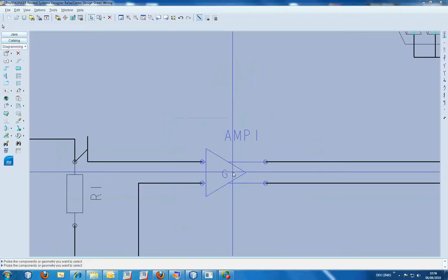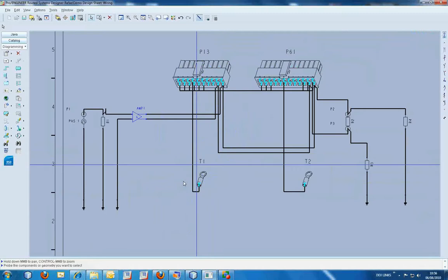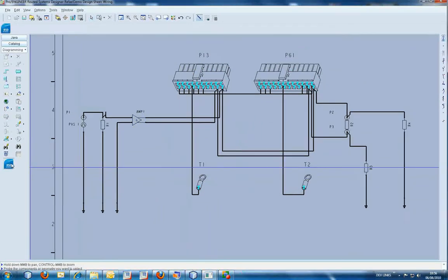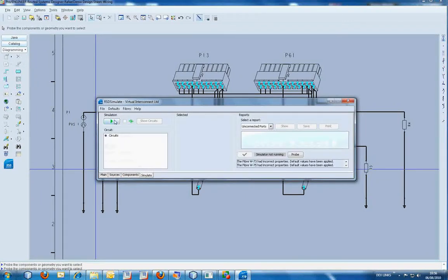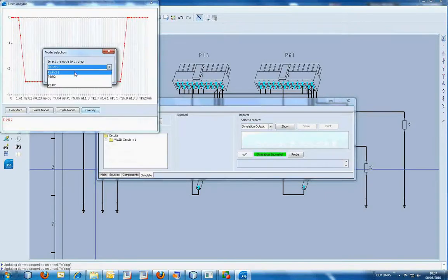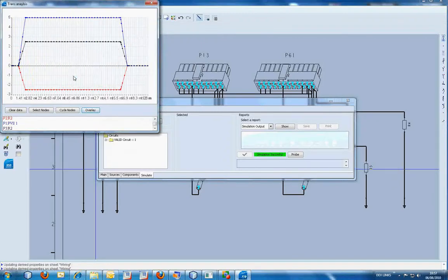And this carries forward into the properties associated to both the circuit and the wiring shapes. As both of these components are linked, if you make a change on one sheet, the change is propagated through into the properties of the corresponding co-shape. And if we run the simulation, we can see that the output we get matches the output we had from the circuit sheet.